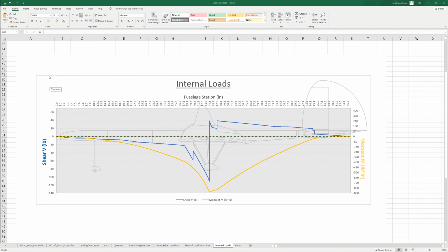So we would build up a final output for the fuselage that would be called an envelope loads diagram, which would be the maximum, at every single point, the maximum M and the maximum V of both signs that could be put on the aircraft by any maneuver. And that overall M and V diagram, clearly it won't be balanced at the end, but that's just a reference as we check the structure at any point along here: what's the max M and V that could occur.